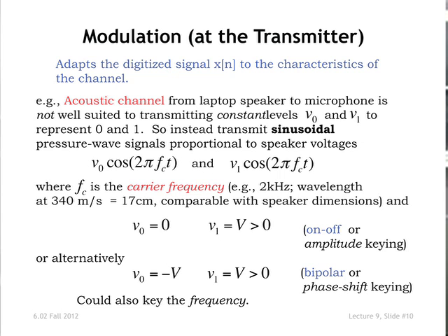So what's typically done is, instead of trying to transmit the DC, you transmit a burst of a sinusoid, because loudspeakers like sinusoids, provided they're at the right frequency. So again, you've got to think about what frequency makes sense. It's this cone trying to move a mass of air, trying to make a mass of air oscillate. There are particular frequencies that are good for that. So you have to think about that.